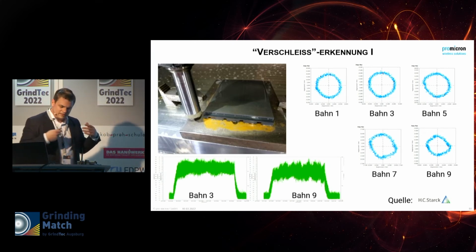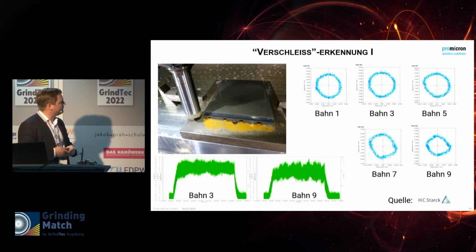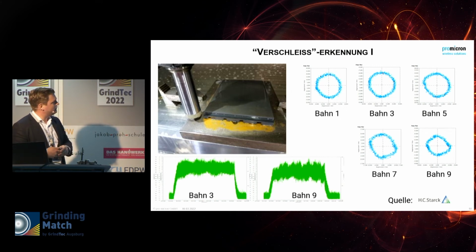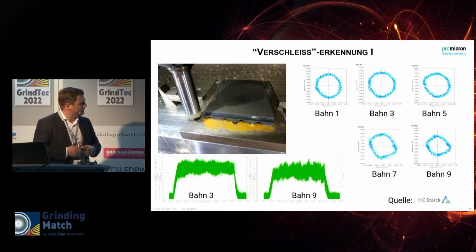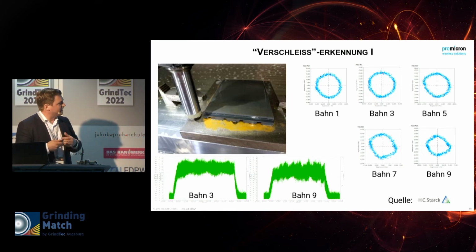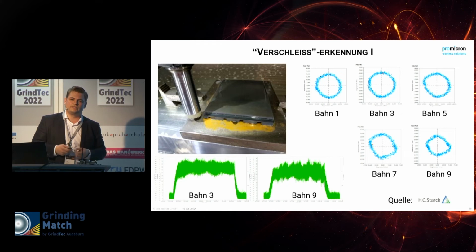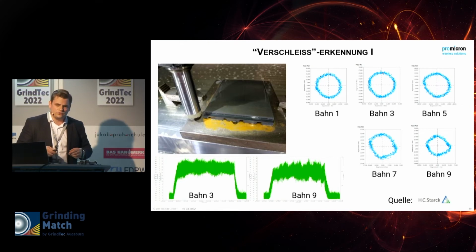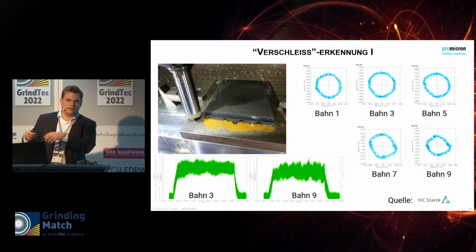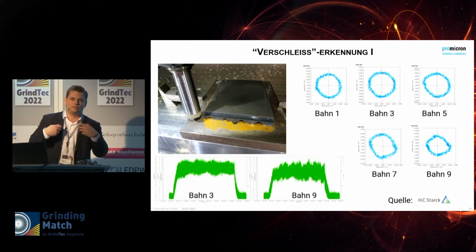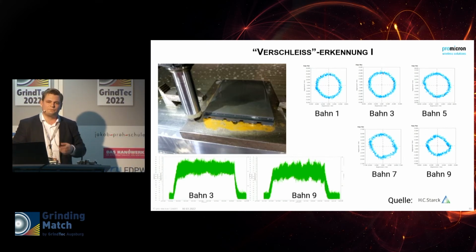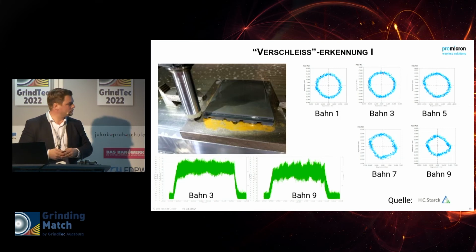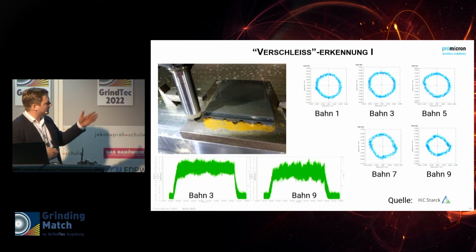This is an example from a completely different grinding area, not just tool grinding, this powderous material in ceramics manufacturing. And the customer just wanted to know when the grinding disc is agglomerated with that much material that it has to be replaced or whatever, or when should the ground object be removed, for example, because of a certain grinding condition.